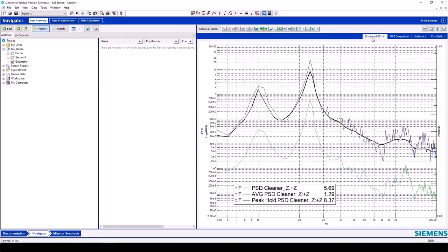The real engineering judgment here is in how much of an acceleration rate. Knowing where you're at on the SN curve can help with what you can expect for a time reduction factor. The slope affects how much we have to increase the amplitude to get a given time reduction.